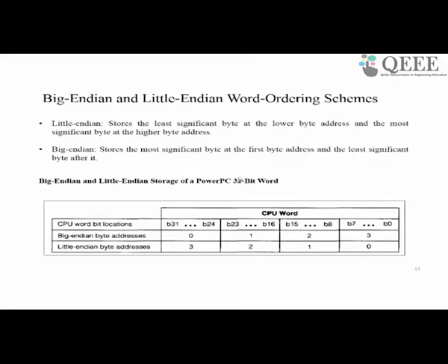Next, when it comes to storing content into the memory and fetching it, we need to look at some other related issues. Normally, the processor reads in terms of 32 bits or 64 bits, which depends upon the width of the data path of the processor. Suppose it is a 32-bit processor, the data bus will be 32 bits wide. It will read 32 bits at a time.